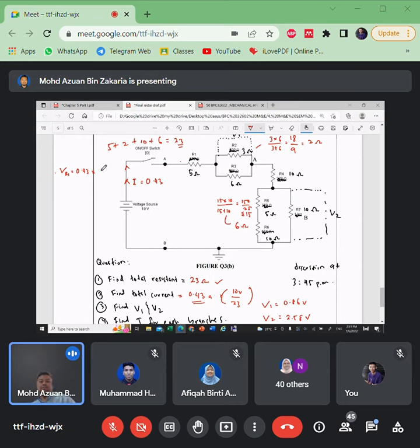Okay, I'll try doing this. Alright, we can calculate straightforward. V1 equals to the resistance, what was it? 2. V equals IR, so we already have 0.43 as I and then R. R at parallel is 2. So we can get V1 as 0.86. Okay, correct.